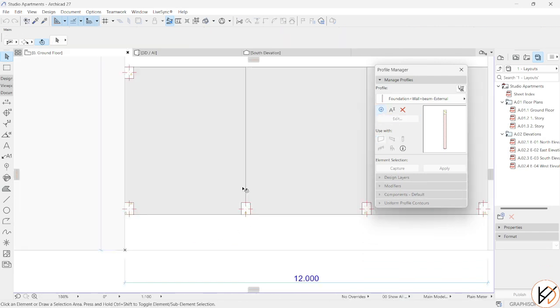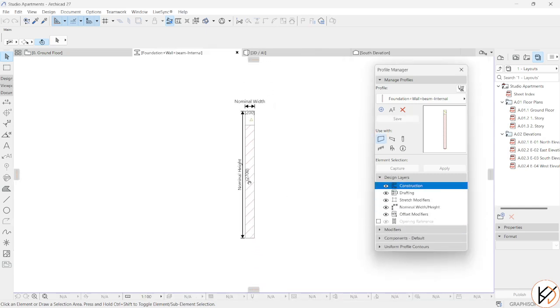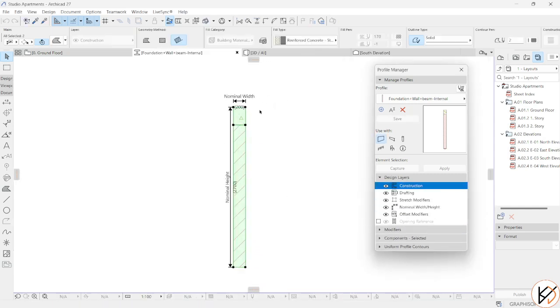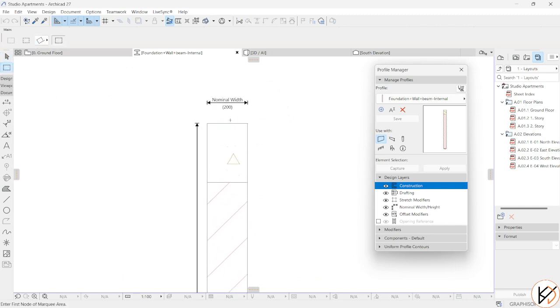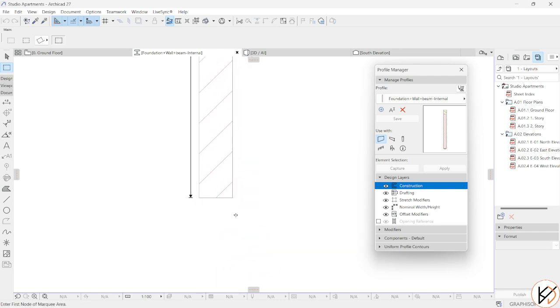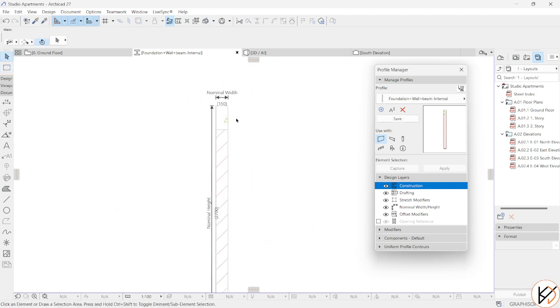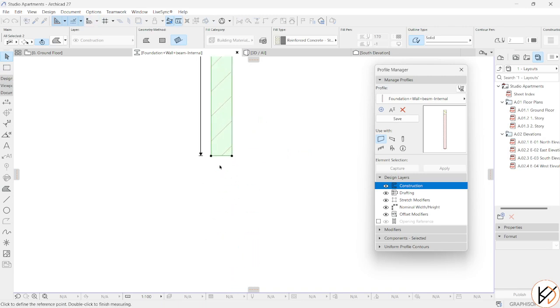And then we're going to duplicate this wall and say internal. Let me label this internal. Okay, and I'm going to say okay. And for the internal one, I'm going to take this marquee tool and use a command called Control Shift H. Technically we'll be shrinking. Control Shift H, we shrink it by 50, and then we drag this whole thing by 25 to the side, so that from the middle, if we measure, we can have 75 on each side.